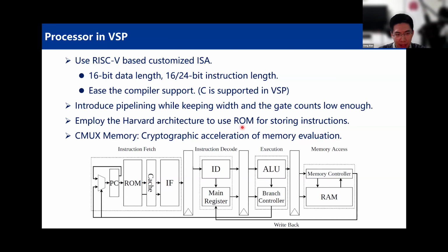And the other thing is that if you think about a memory, it's basically address decoding and data fetching, and the most amount of computation happens in the address decoding, because you have to decode binary-encoded data into an exact one-hot representation to select the thing you want to read or write.